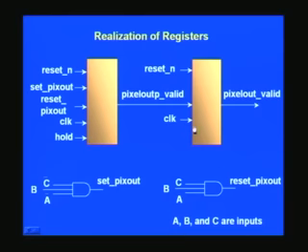And we have one more flip flop here that also has similar signals, for example reset and positive edge of clock, and just as we have this pixel out, we have a P, we have a pixel out here. Actually this is the signal that we want, and this is actually a signal pertains to a previous clock.